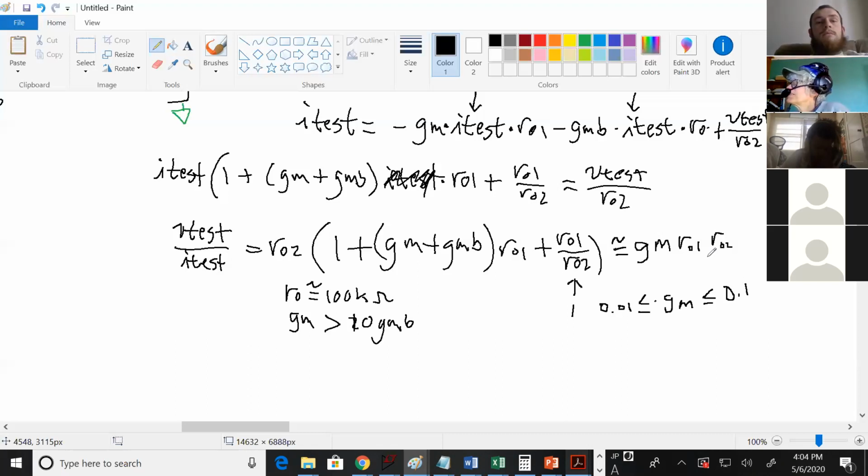Got it. Yeah, and I'll give you the moral of the story on Friday, just because this is so useful. Cascoded transistors are any place you need a big resistor, just stack a couple transistors and you've got gigantic resistance, or perceived as gigantic resistance.